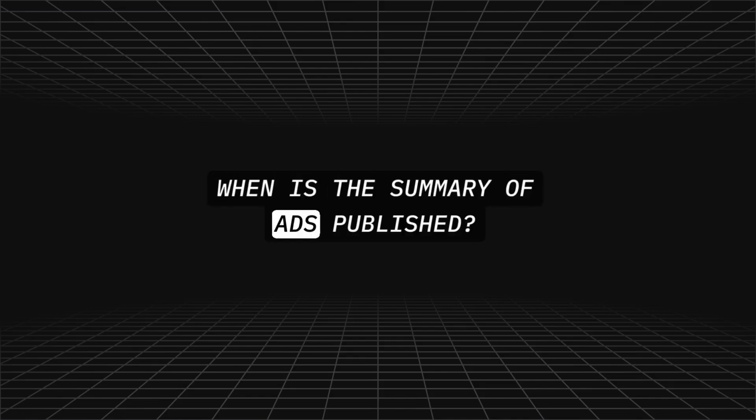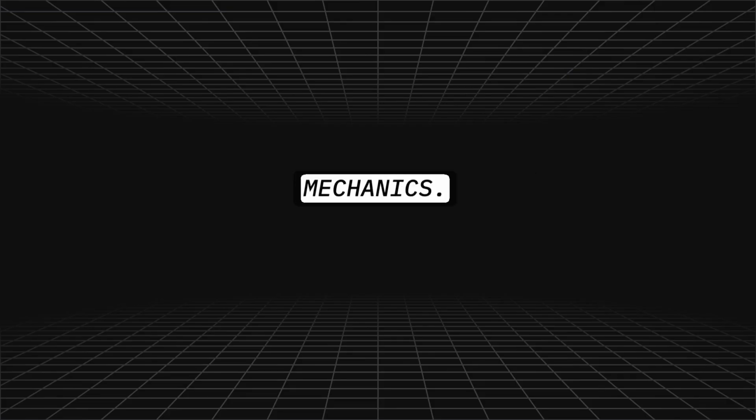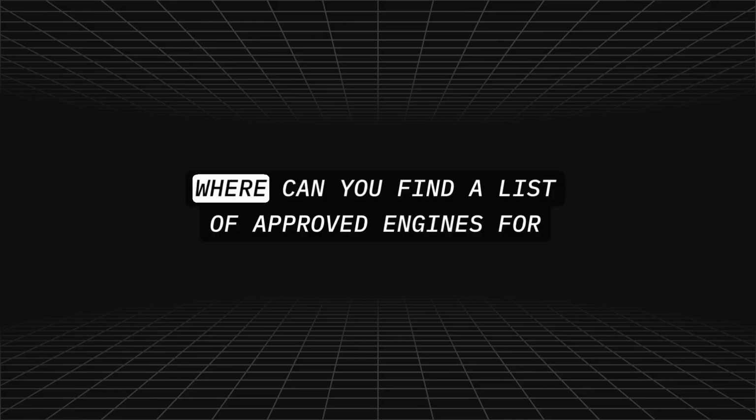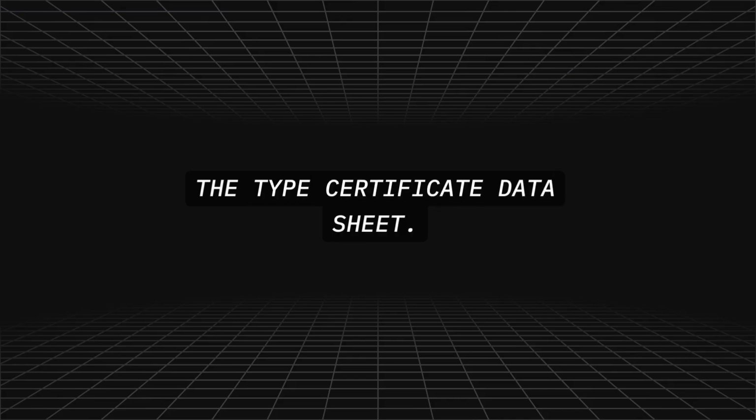When is the summary of ADs published? Every other year. Are ADs automatically issued to certificated mechanics? No, they are issued to owners. Where can you find a list of approved engines for use in specific model aircraft? The type certificate data sheet.